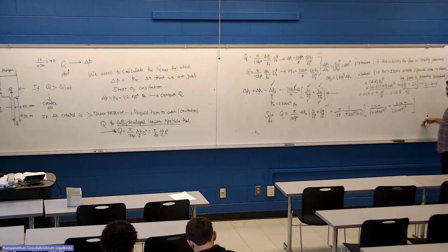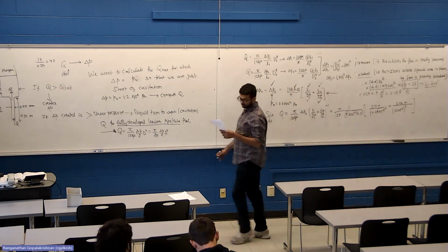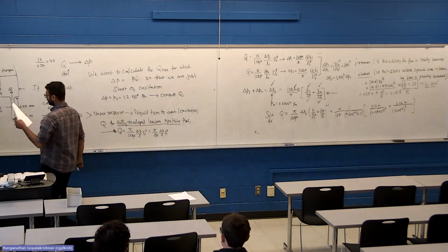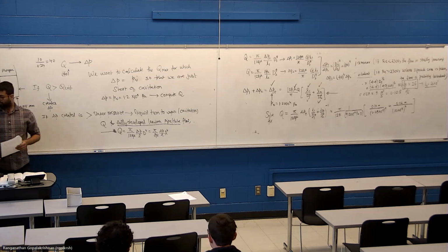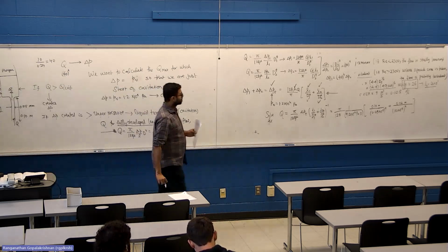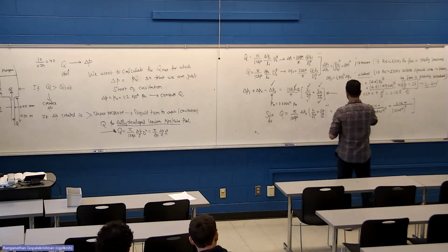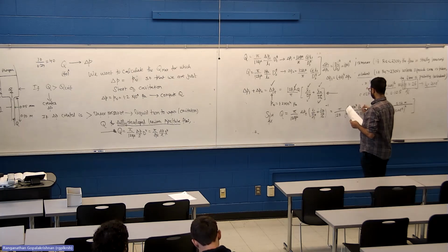Where'd you get 0.02 from? So in the figure, the needle portion is set at 0.10 and the total length is given to be 0.12. So I took the difference. Yes, you then multiply by delta P. So delta P would be 1.2 times 10 to the 4 pascals.